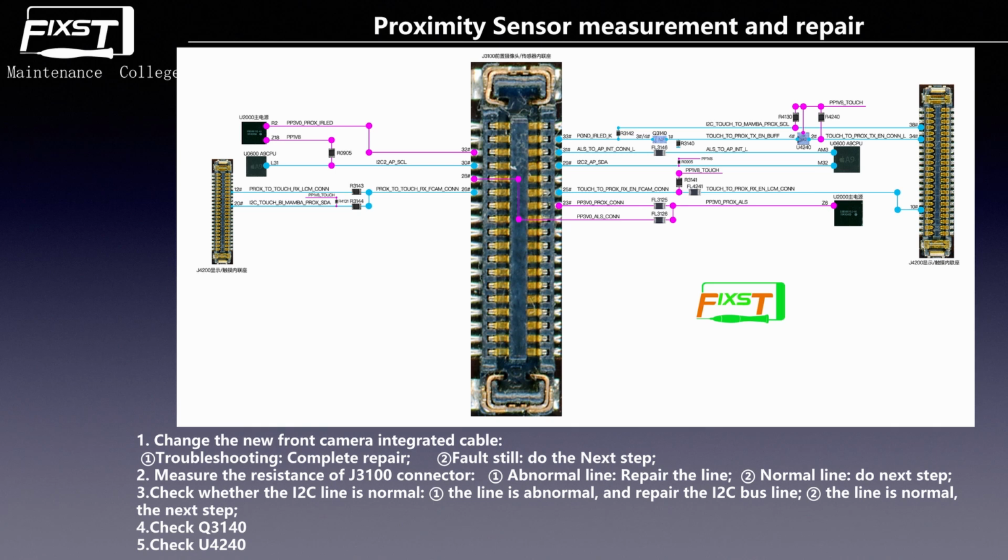These two loop circuits, together with the pin 3 line, become a full circuit to give the power. And as you can see, this power is sent by the U4020, the backlight booster IC. The backlight booster IC uses the A1 pin to send the power to the connector, the pin 3. If there is just one power line, the LED cannot turn on, so it needs to become a loop circuit, going to pin 3 and pin 1 and becoming a loop circuit.